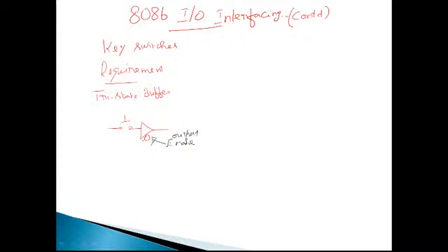Since you are seeing a bubble here, when this signal is equal to 0, the output is enabled, that is, the output follows the input. Whereas if it is 1, the output is disabled. More aptly, we can say the output is at tri-state, otherwise called the high impedance state.